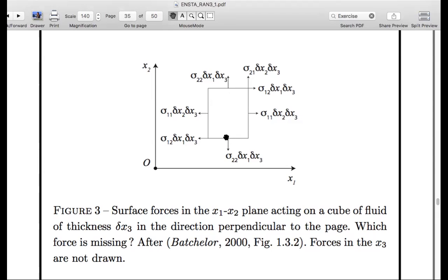Well, what I want to say is that's just -1 times the force when the normal is in the y2 direction. Because my normal is in the -y2 direction, my force per unit area will be in the minus x2 direction. Did I say y2 direction? Yeah, I meant x2 direction, which is the y direction if you're using xy.